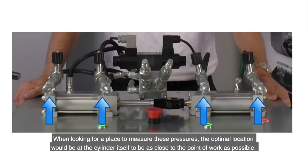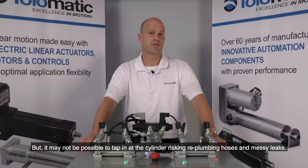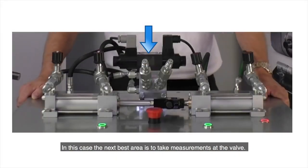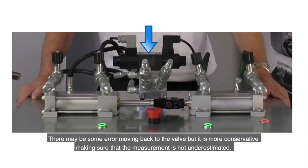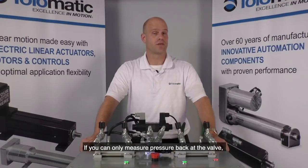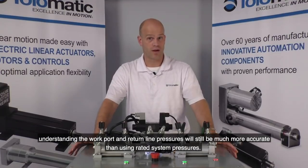When looking for a place to measure these pressures, the optimal location would be at the cylinder itself to be as close to the point of work as possible. But it may not be possible to tap into the cylinder without risking replumbing of hoses and messy leaks. In this case, the next best area is to take the measurements at the valve. There may be some loss moving back to the valve, but it is more conservative, making sure that the pressure measurements are not underestimated. Even if you can only measure pressure back at the valve, understanding the work port and return line pressures will still be much more accurate than using rated system pressures.